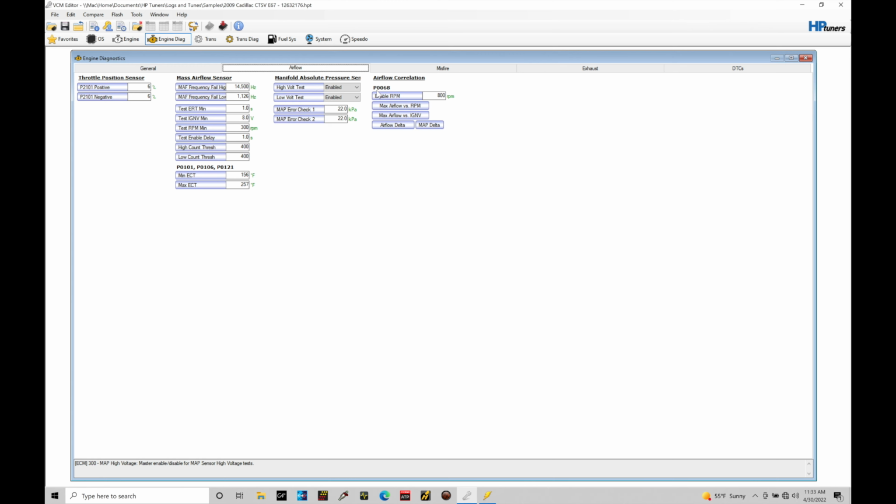So if this code gets thrown, it puts the engine control module into a limp mode. It's going to try to shut the throttle plate down. It's going to try to limit what the engine is doing to prevent that runaway throttle situation. We want this in place again to make sure we're not going to get into a situation where somebody's going to get hurt or we're going to damage property, damage vehicles. We want to make sure that this is always enabled after you've done your calibration.